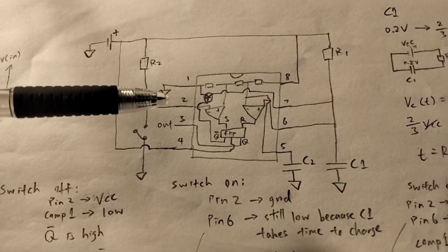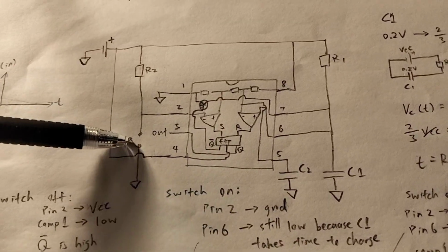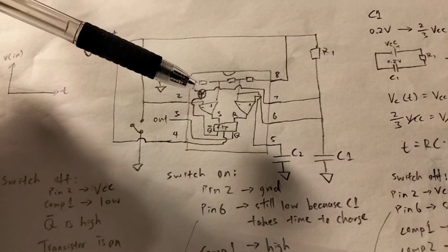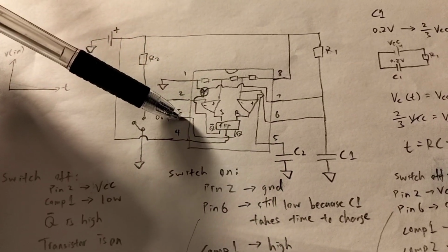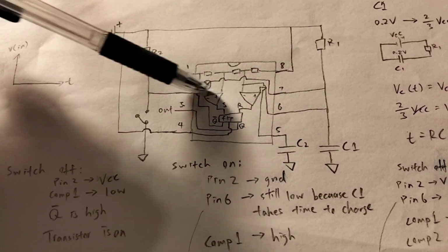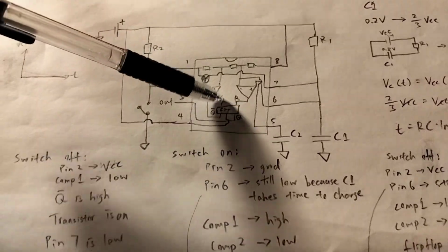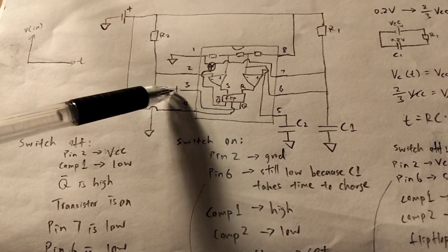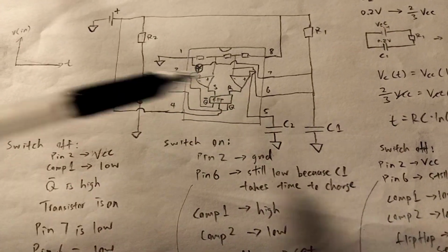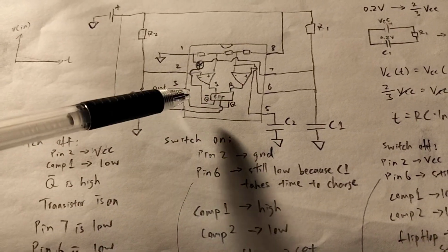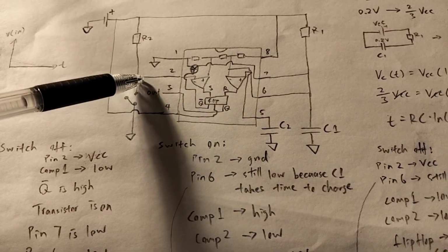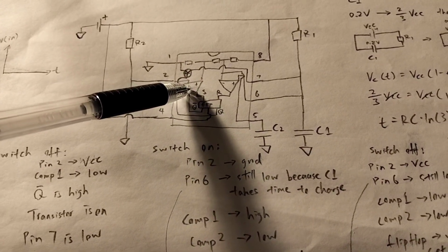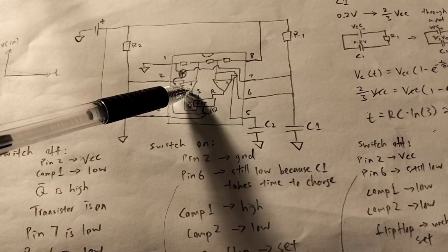The other thing to note is that if we press and then immediately release, the expectation is that the output is going to light up straight away, because this comparator straight away starts to output high, the flip-flop turns high, and the output is high. And then when we release, the set comparator is going to be low.